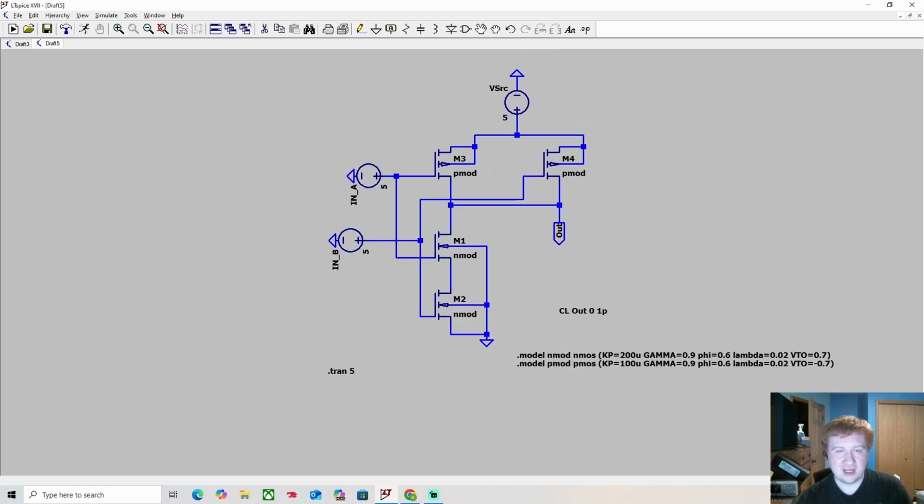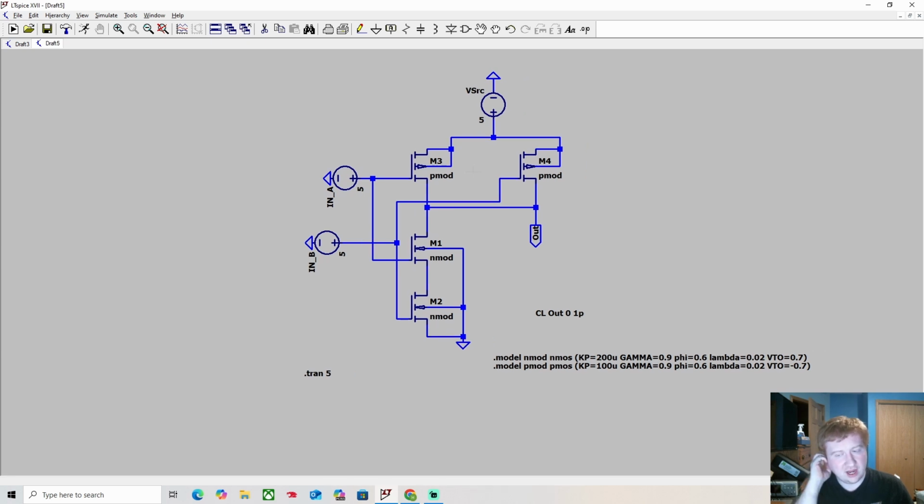For these logic gates, we don't really consider that, because again, most computer systems or breadboard Arduinos and stuff like that, you're limited to basically 20, maybe a maximum of 50 milliamps per digital port. They can't really reach that level. And they probably don't use MOSFETs either. They probably use NPN transistors most likely.